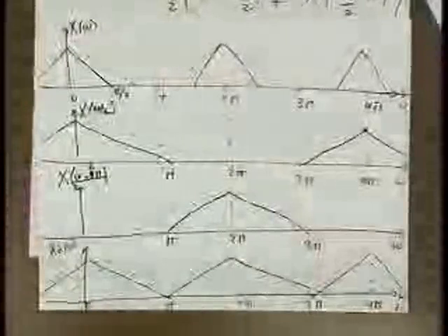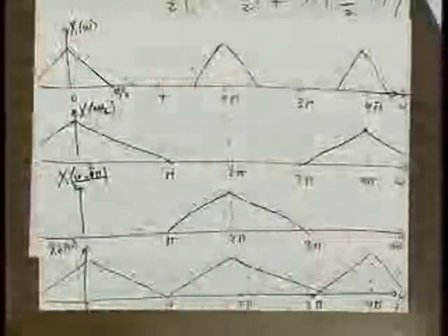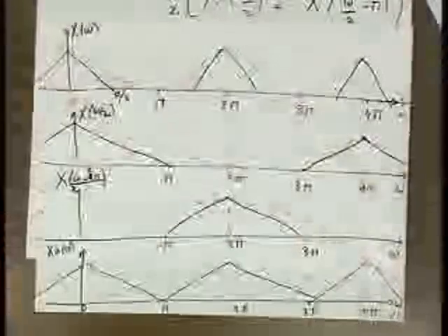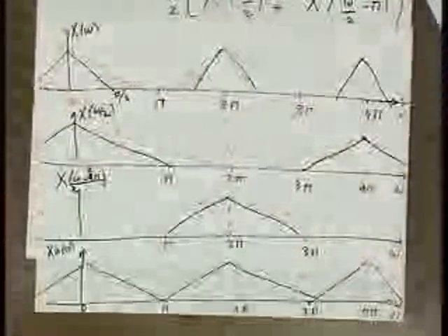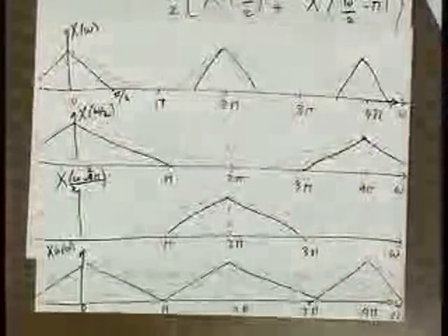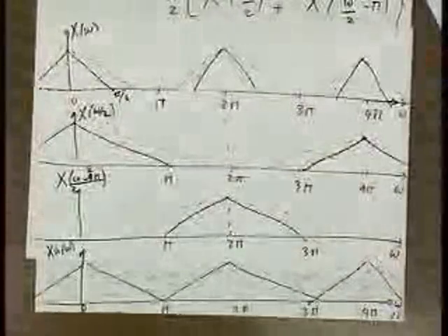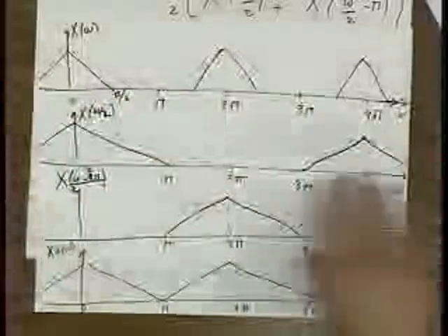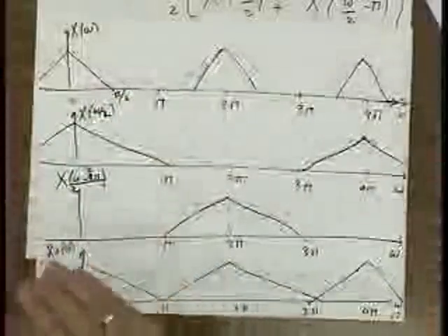If you just sample something at the bare minimum so that it's barely non-aliased, and then downsample it by a factor of 2, you're definitely going to alias it, right? Because to begin with, it was just barely not aliasing. So this confirms the intuition you've accumulated in the course.